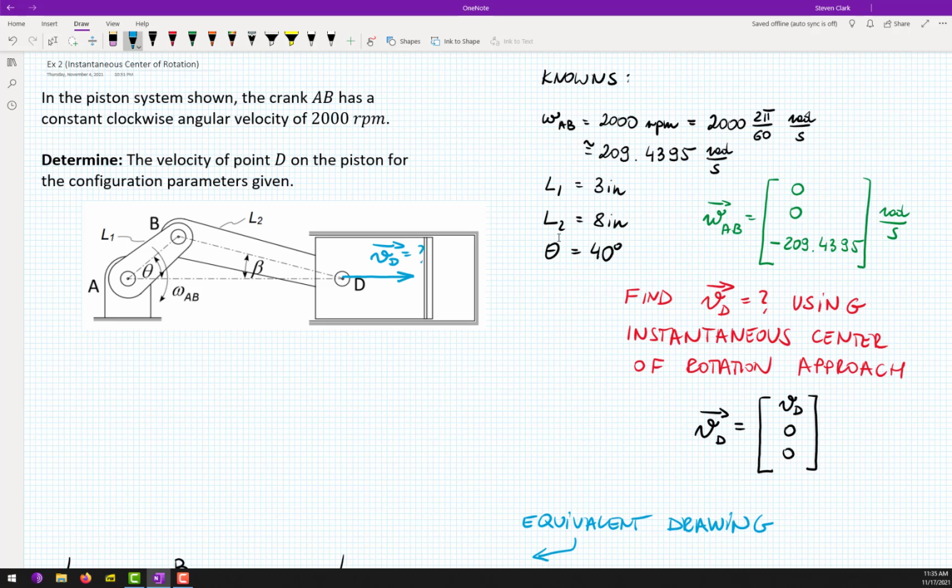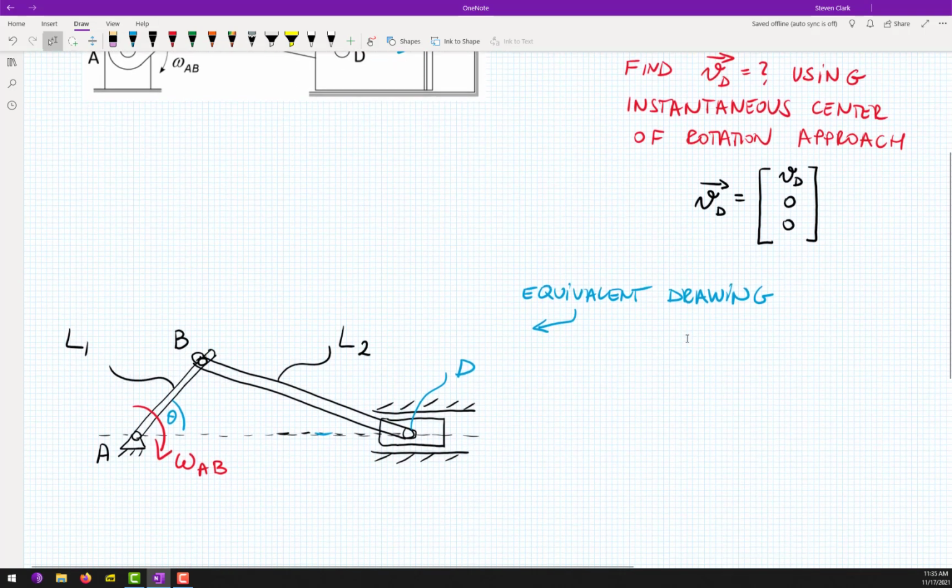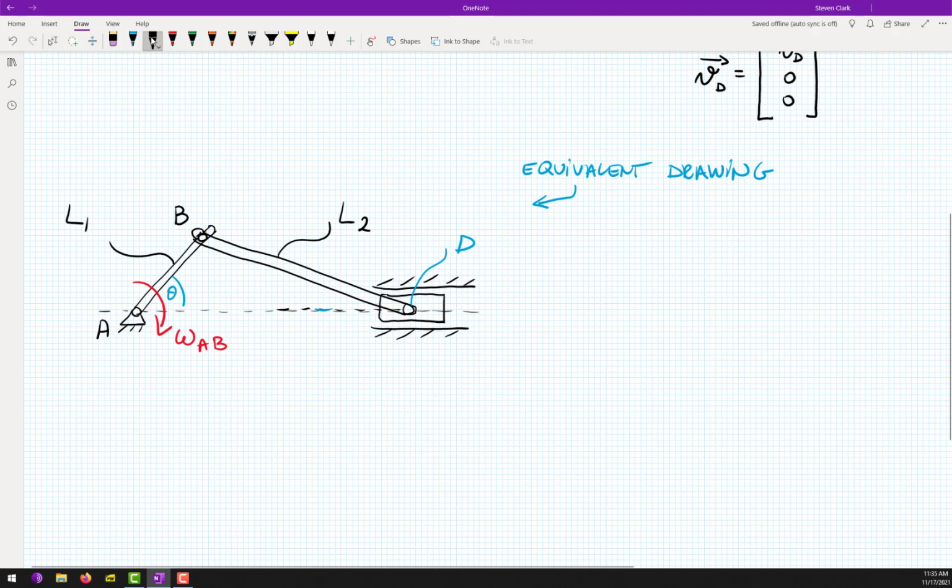It is not known. In the previous video, you've seen the velocity analysis approach. Today, we're going to do the geometric approach. So how would I like to tackle it? I would like to find the IC of bar BD. So let's find the IC of bar BD. We're going to follow the recipe. We need to find 2 points and 2 velocity vectors attached to these points.